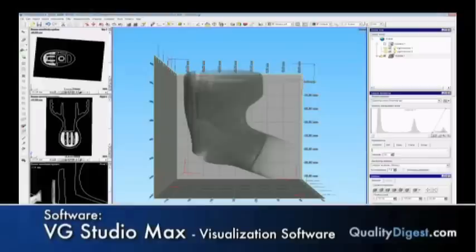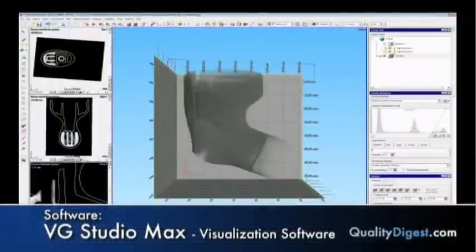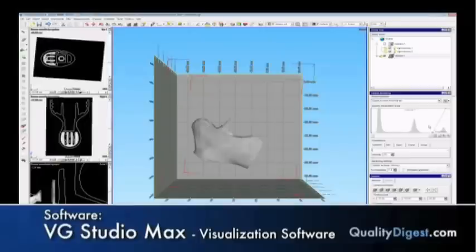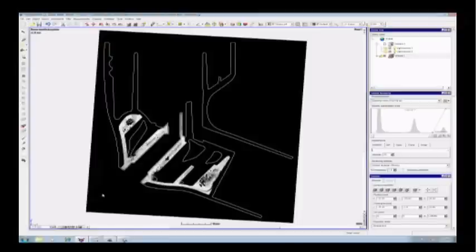So what you're saying is basically you're doing this manually using the histogram, selecting which opacity you want to look at. Okay. Exactly, which opacity I would actually want to focus in on. Okay. And I also have the ability to virtually slice through the part. So I can cut through the part just like I'm cutting it normally on a CNC machine, so now I can go into any 2D projection and walk through the slices. As you're walking through, as you can clearly see, there are some really large voids inside this part.